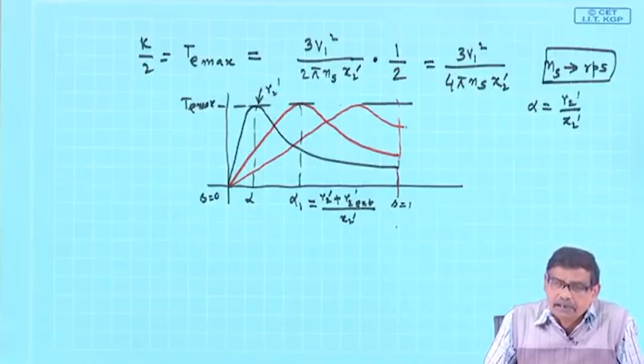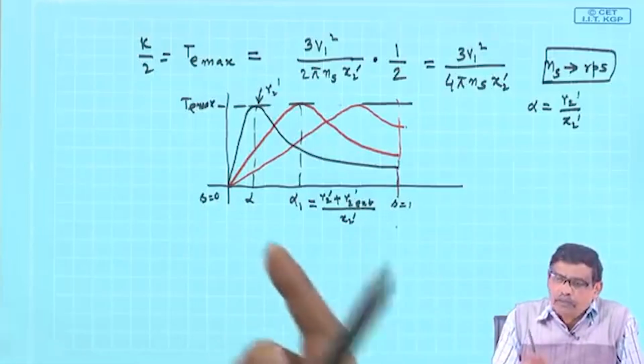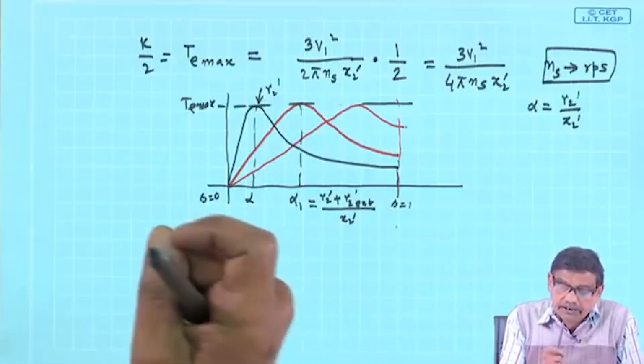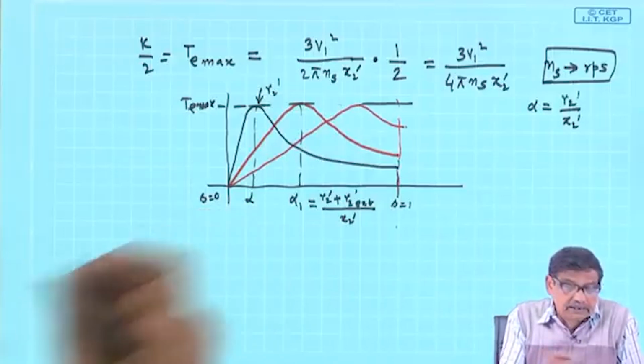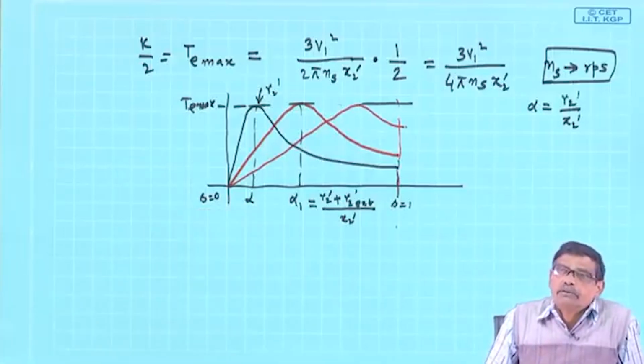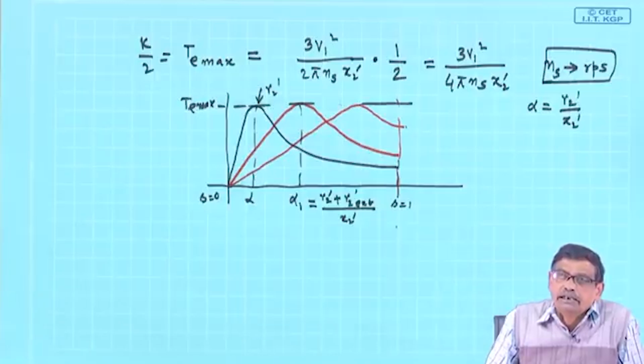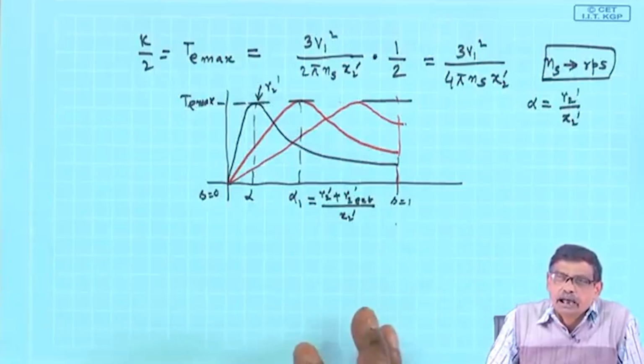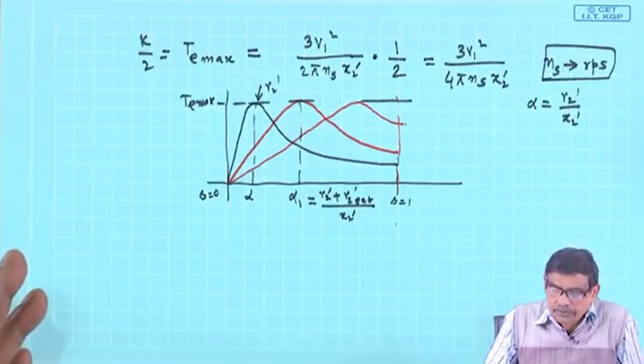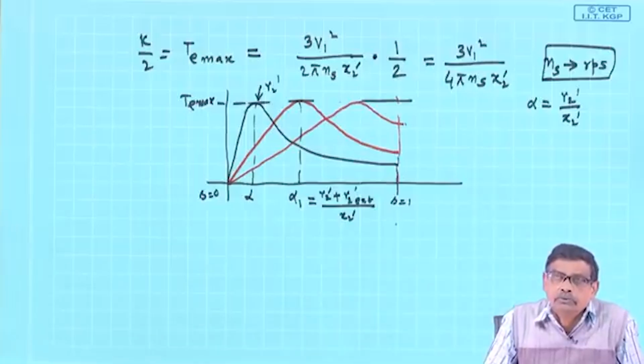So, I will calculate the value of the slip and substitute that value of the slip in the appropriate formula to get the torque, and how much mechanical power it produces, the amount of torque into 2 pi nr. All these things I can do at any value of slip you want me to do that.